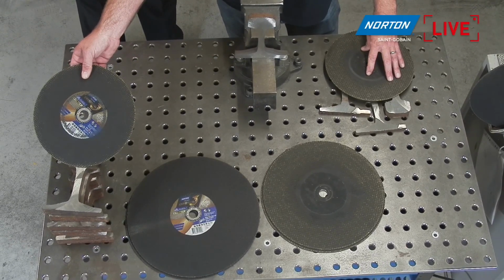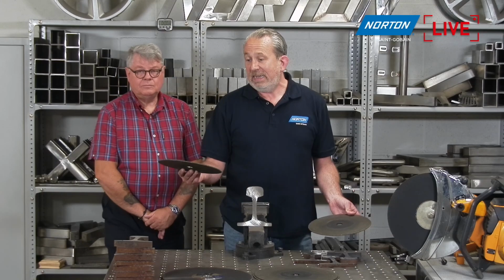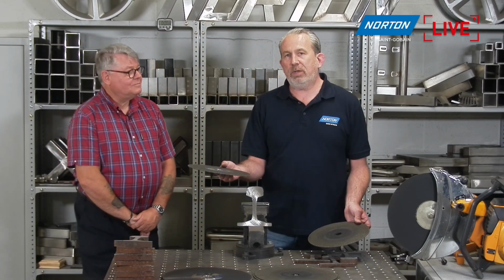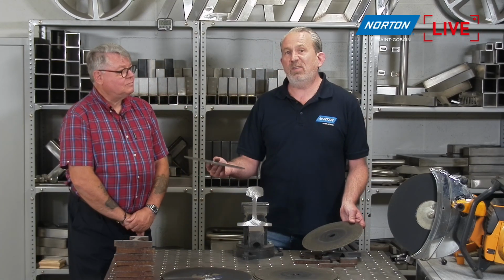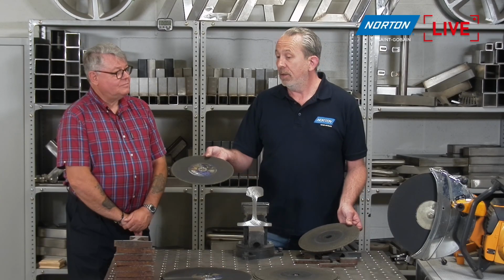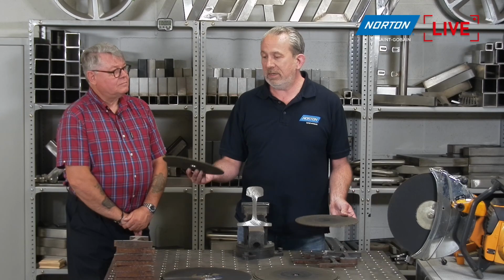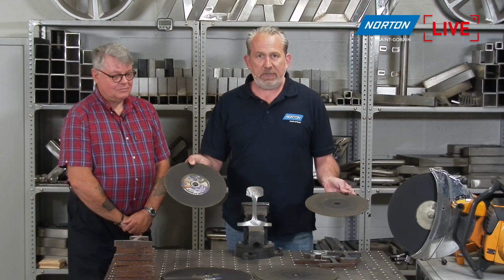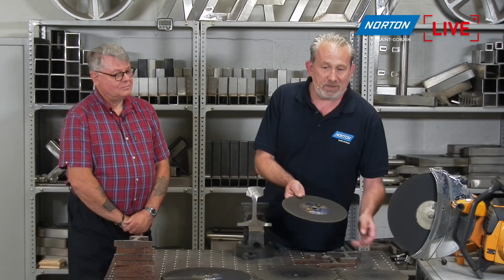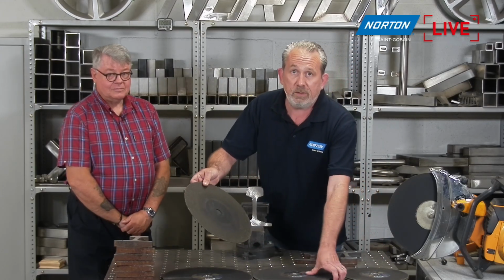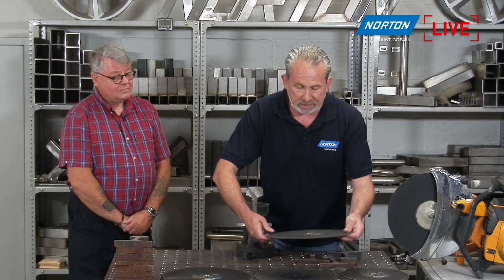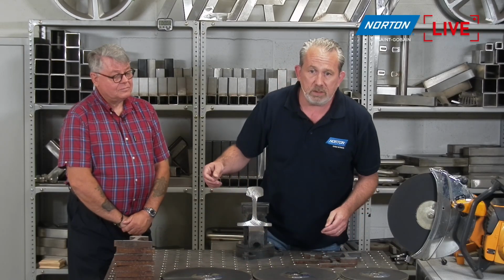So we end up at the same diameter, which is about 300 millimeters. At this point, you can't effectively cut anymore because you can't get through the foot of the track from either side. So now at 300 millimeters, that's scrap. But time to change, yeah, time to change, time to get a new blade on. But 8 cuts versus 3, it's very obvious the performance difference that you get there. And that's all down to the bond technology and the ceramic grain inside the Quantum 3 cutting disc.